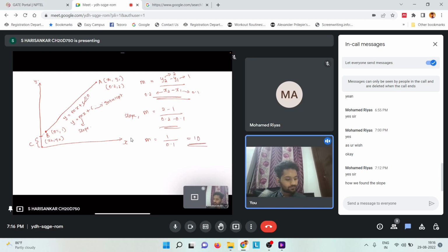Okay, so the last question, y equal to mx plus c, we said this c is 0. So this y is basically the rate N, and this x is basically the moisture content on dry basis X. So just substitute the value for slope here. N is equal to 10X. This is how we got the equation for slope, or the equation for the falling rate.